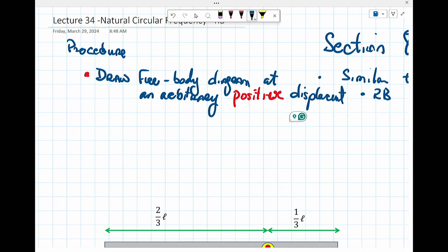You want to set up the equations so they look a certain way. The terms, mx double dot plus kx, has to always be mx double dot plus kx. If you end up with minus kx, your solution will not work. Again, we're not doing a lot in terms of analysis. We're just taking the free body diagram and working from there.